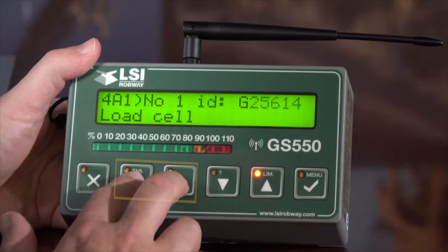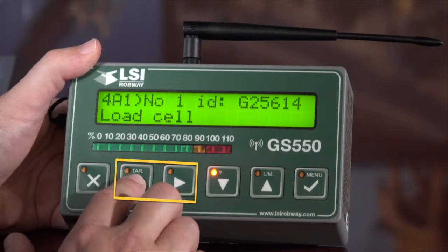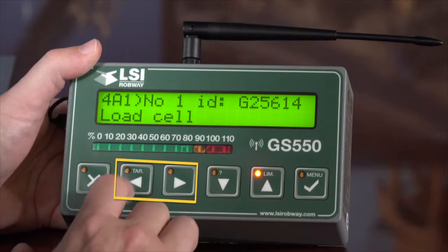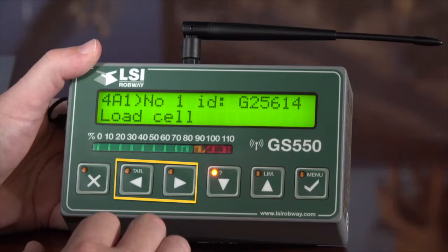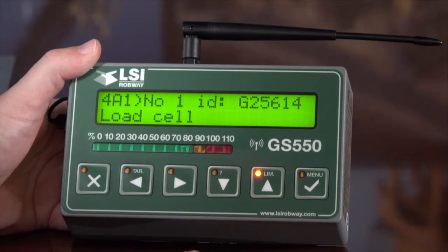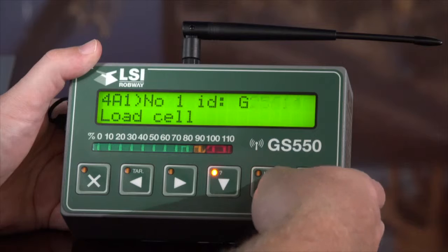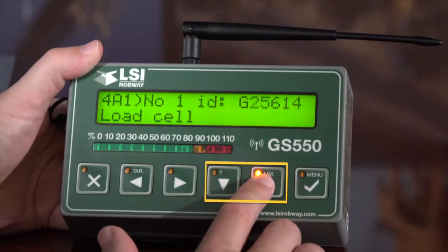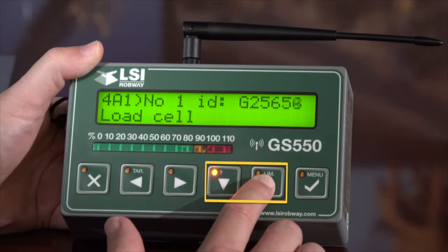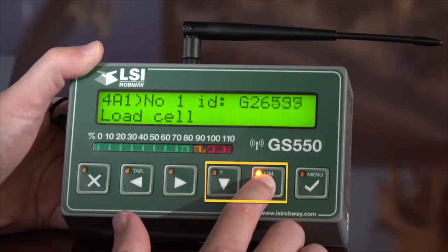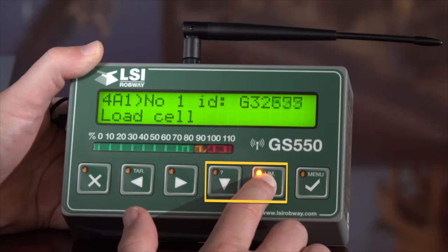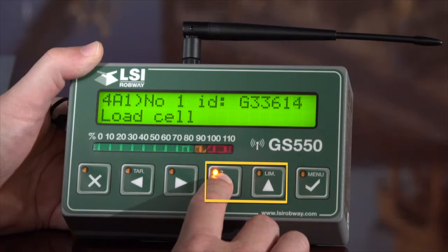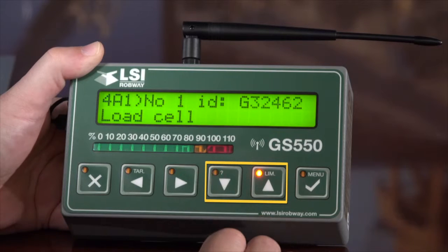Now to modify, you press the right arrow or the left arrow. Whichever portion is blinking, that is the field that is set to modify. In this instance, we just want to change the ID number to a new load cell. To do that, use your up and down arrow, just press and hold, and you can see how the numbers start scrolling. And it'll start scrolling pretty fast, so if you get to the number and you pass it, no worries. Just use your down arrow to go back the other direction until you find the proper number.